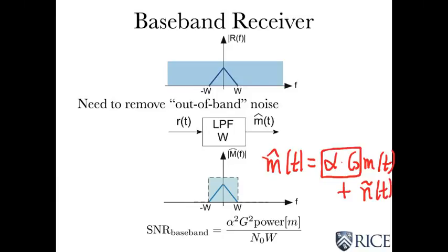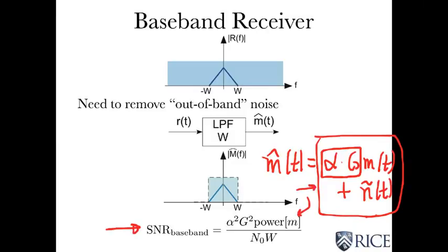This corresponds to the knob on the radio, a volume control, if you will. We'll make up for it by amplification a little bit later. But if you amplify this entire signal, multiply it by a constant, you do not change the SNR. So we can study the SNR for this signal as it is, and that will be sufficient to characterize quality. And we will fix the gain problem, if you will, by further amplification.